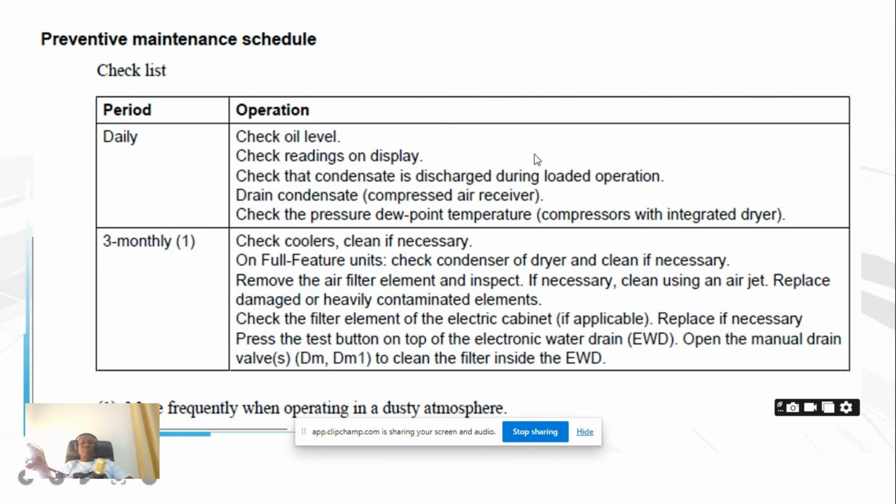Okay, and you can see if the condensate is discharging. You see it on your own. Then check your dew point for a compressor which is integrated with a dryer. Some compressors have an inbuilt dryer to dry the air, while some do not have an inbuilt dryer.